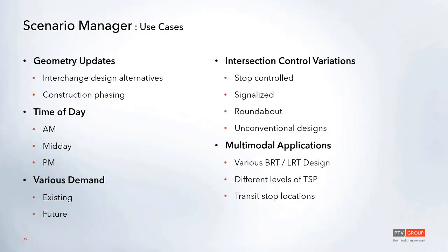So here are some different use cases for Scenario Manager. You could use this for geometry updates, like an interchange design or different construction phasing. You could also use this for time of day. So maybe you have AM versus PM, or maybe looking at different demand years, like current 2020 versus maybe 2035. And also for maybe upgrading different intersections. So maybe you have a stop controlled intersection and you want to look at signalizing that, or maybe using a roundabout.